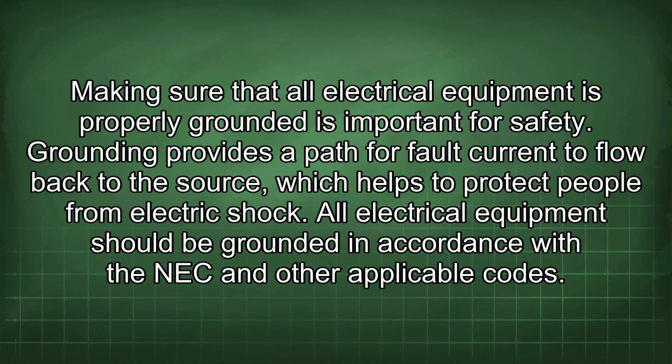Making sure that all electrical equipment is properly grounded is important for safety. Grounding provides a path for fault current to flow back to the source, which helps to protect people from electric shock. All electrical equipment should be grounded in accordance with the NEC and other applicable codes.